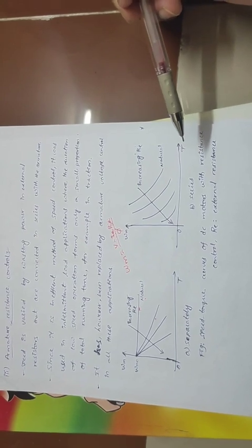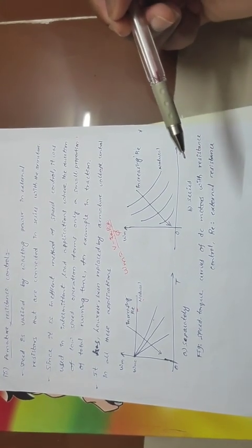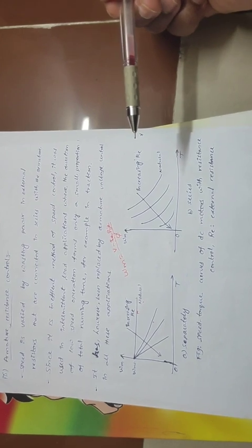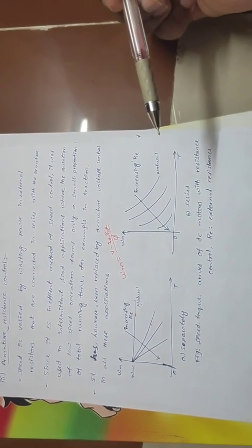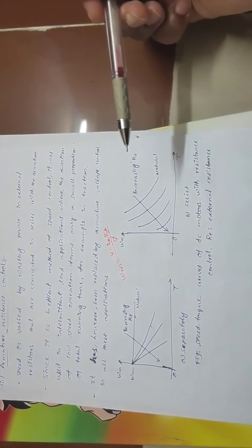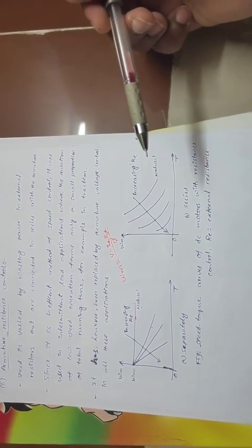So this is an inefficient method because we are wasting power in the armature resistance. That's why in practice we don't use this method.